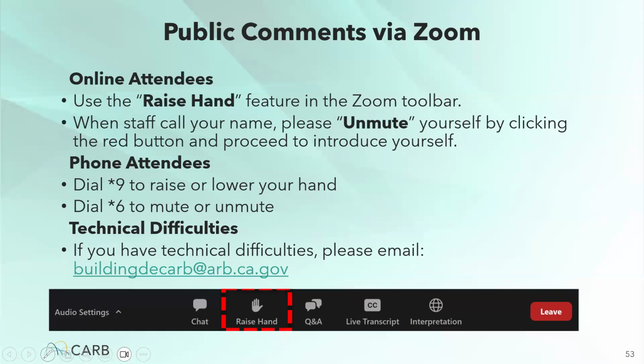And my third comment is, with respect to multifamily units on slides 39, 40, and 41, I'd encourage you to relook at those assumptions on the moderate and the extensive retrofitting costs. When considering panel sizes, the conductors to the panel sizes, the conduit fill limits you are required to follow, and then the transformer and the switchgear, all of which in some cases you're doubling capacity, or you're trying to make assumptions relative to what kind of new panel capacity technologies are going to work.